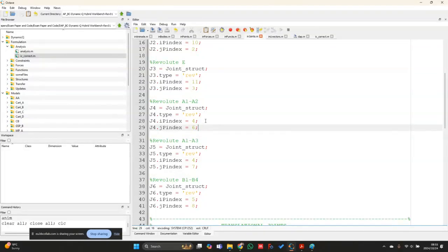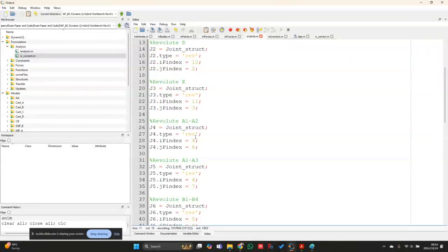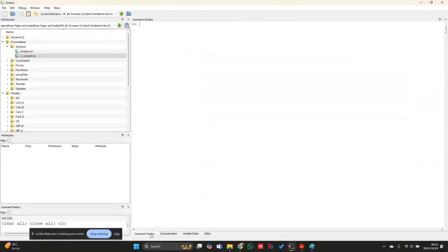The first row in this case is going to be the X reaction force, the second row, the Y reaction force. So if I quickly check over here, this would be 2, 4, 6, 7 that I want to extract. And then 8 is the Y value. In the case of A1, A3, that would be 9, which corresponds to the X reaction force again. So 7 and 9 are the two Lagrange multiplier indices that I want to use. But I also need to go and take into account the Jacobian. So the Jacobian tells me what the sign of that specific reaction force is going to be.